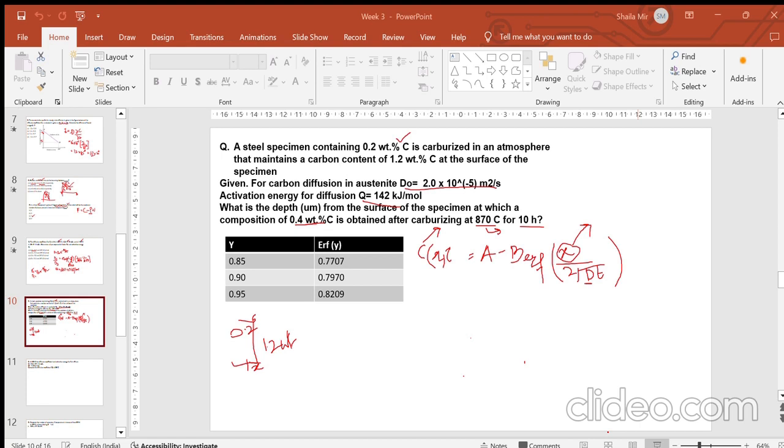This is very important if you go for heat treatment or hardening of steels. So this will help you understand how thick that layer is, which is why we say the mechanical properties are improved because of carburization. You can take 1 minute and find the x value. Just put the values and find it.